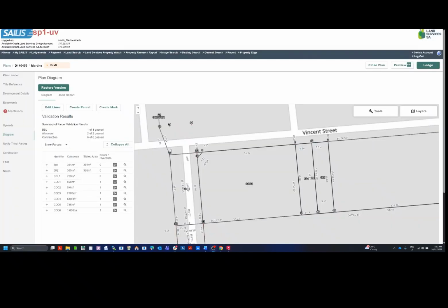Some additional drafting practices to help with data processing for your closures reports. Draft a single diagram in model space with one set of parcels and one set of parcel identifiers to prevent duplicate parcels in the closures reports. Ensure that the MGA zone in the title block matches the coordinates that the geometry of the diagram has been drafted in model space. If you are required to show a second bearing datum, show it on the A general layer on the sheet, not within the title block.